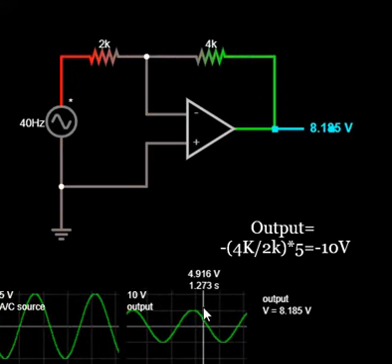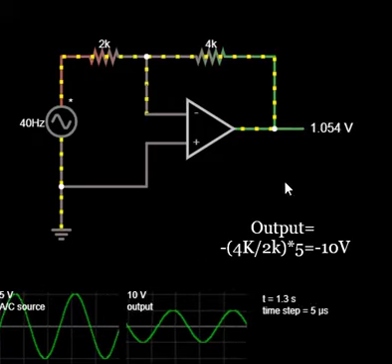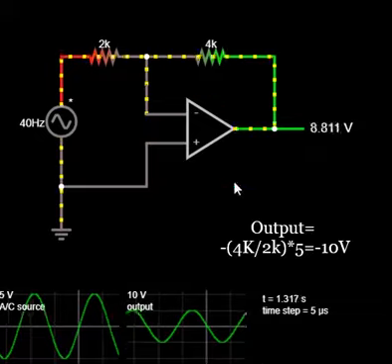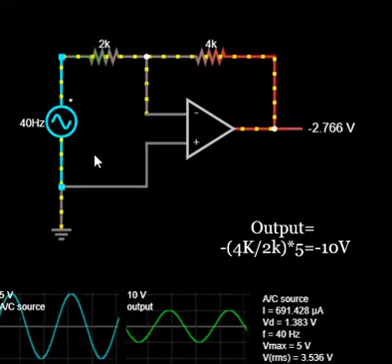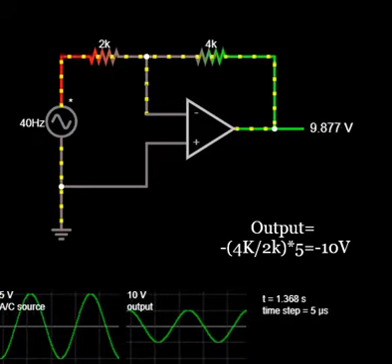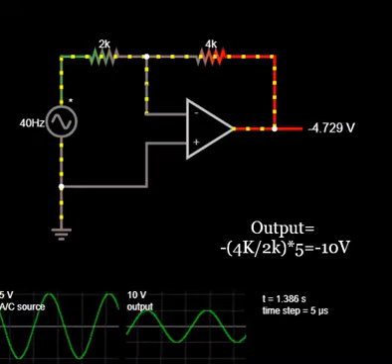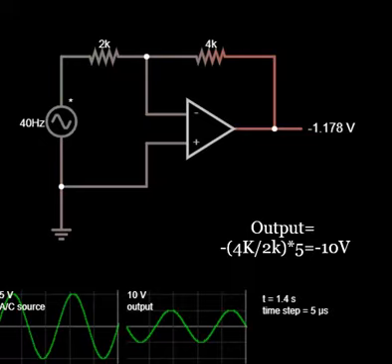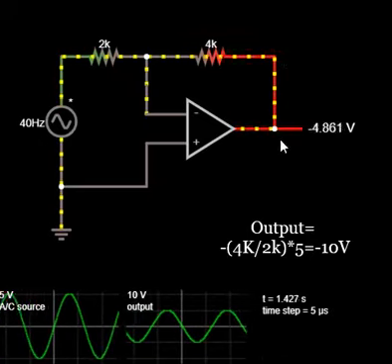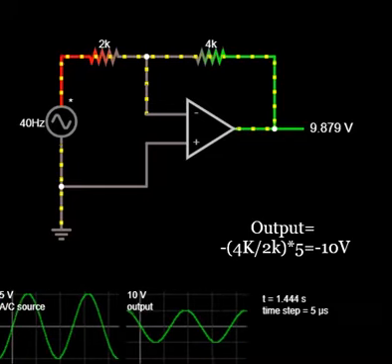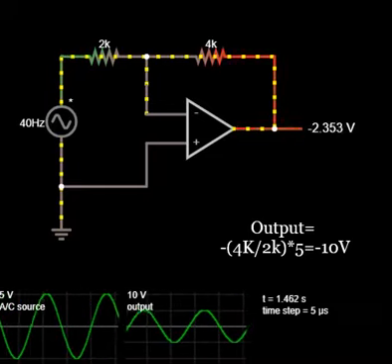And this output voltage will vary, and the circuit also shows the way the current flows in the circuit. If you observe, into the op amp input terminals there is no current flowing. That is because ideally we consider the value of the input bias current to be equal to 0, and that is very clearly evident in this particular circuit. You can see the flow of current. It is from the sinusoidal signal through the feedback path from the output and back to the input.